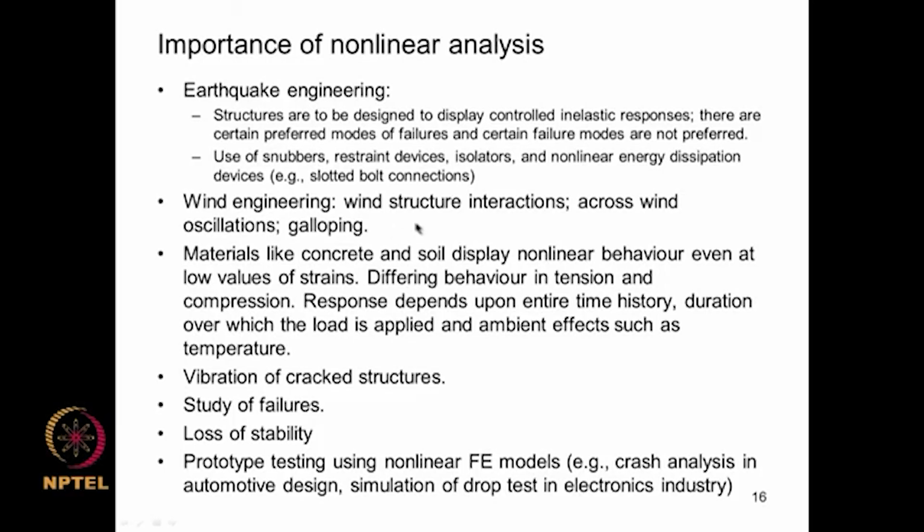Similarly, in wind engineering the interaction between structures and the flow past vibrating structures induces highly nonlinear forcing functions, which I will briefly mention in one of the next slides. Materials like concrete and soil, which are important in civil engineering applications, display nonlinear behavior even at low strains. So, the response need not be very large before nonlinearity is switched on. Also they display differing behavior in tension and compression. Then response depends upon the entire time history, the duration over which the load is applied, and ambient effects such as temperature.